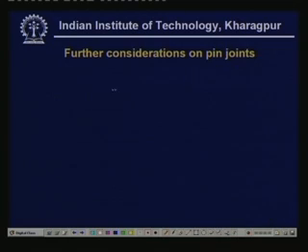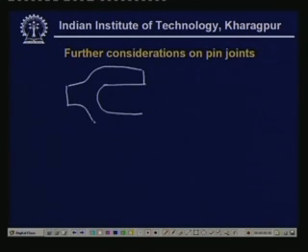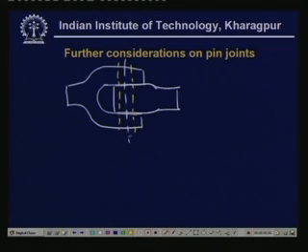In the knuckle joint we have used, so knuckle joint was something like this, where a pin is inserted over here. Now, in that case, this was subjected to tension. Now, this is the joint where two members are restrained against the tensile force. Sometimes this pin is also used when you want to fix two shafts when a twisting moment is applied. So, this is a different pin arrangement.